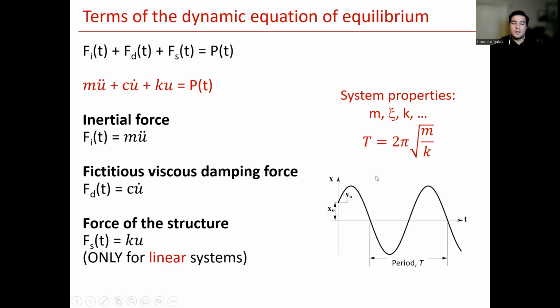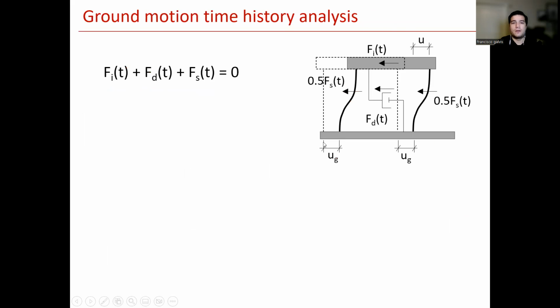And that's really interesting, because what it says is that if you leave that single degree of freedom system and let it vibrate freely, then the time it takes for one complete oscillation, crossing here, going all the way to the negative side, all the way to the positive side, and crossing again, is exactly the one you can compute based on the mass and the stiffness, right? So you need only two parameters, period and damping coefficient, to describe the vibration of a single degree of freedom.